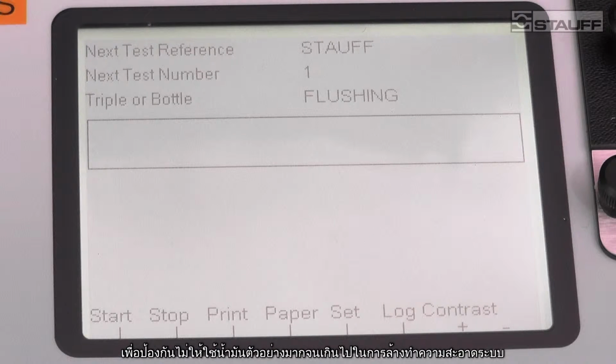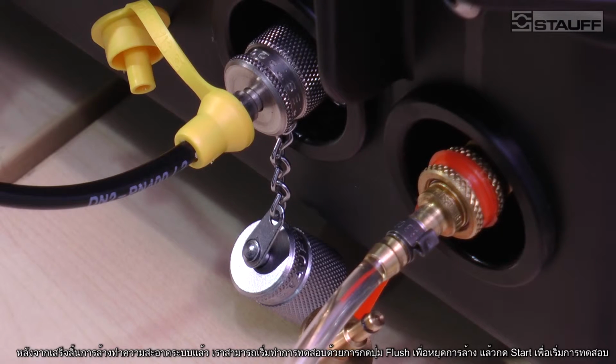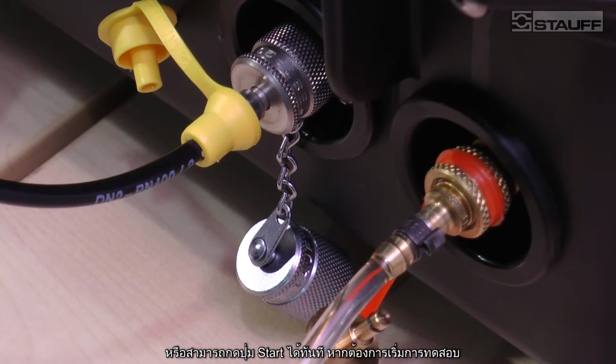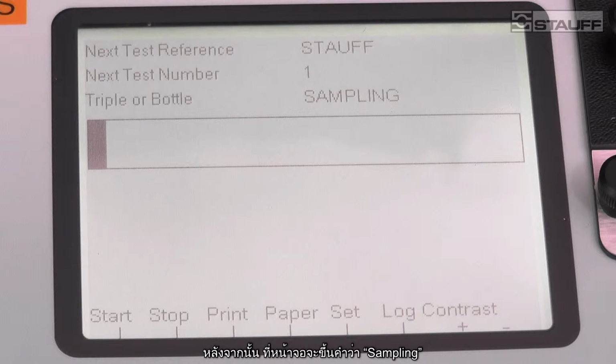So now we've flushed the particle counter, we can press the flush button to turn it off, or we can immediately press start. When you press start, valve automatically closes. So now the machine shows us sampling, and the progress bar also indicates the progress of the sampling.